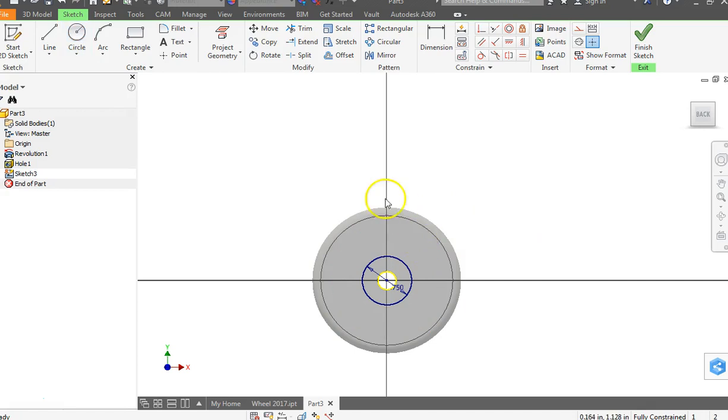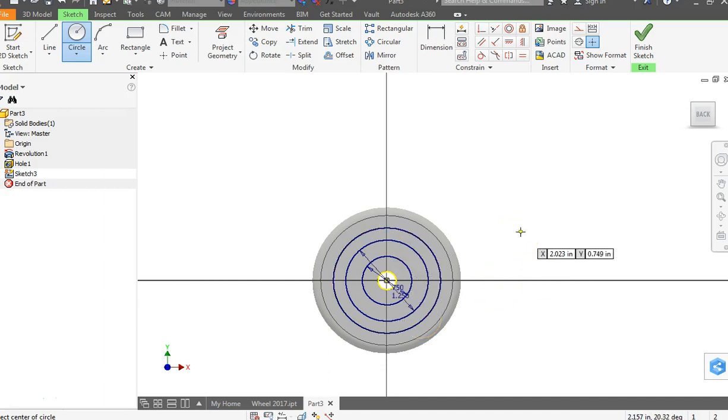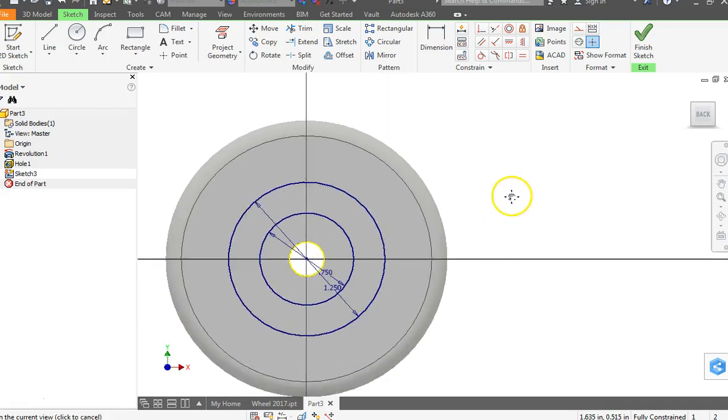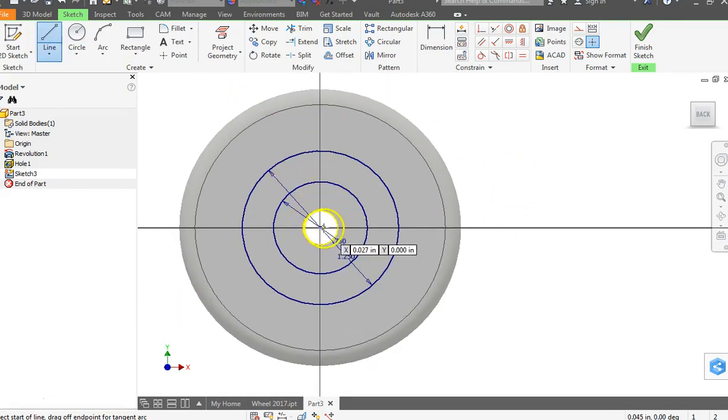I don't know what that circle is. There you go. Okay. I might have clicked accidentally. So 0.625 times 2. There you go. And so we're going to build, I'm going to use the line tool. Right here, if I go straight up, the degrees is 90. I'm going to walk this way, 15 degrees. So 90, take away 15 is going to be 75. I'm going to hit tab to go to the degree and make that 75. I'm going to make a line tool again, also from the center. Come over here. Tab. 105 is actually perfect. 90 plus 15 is 105.